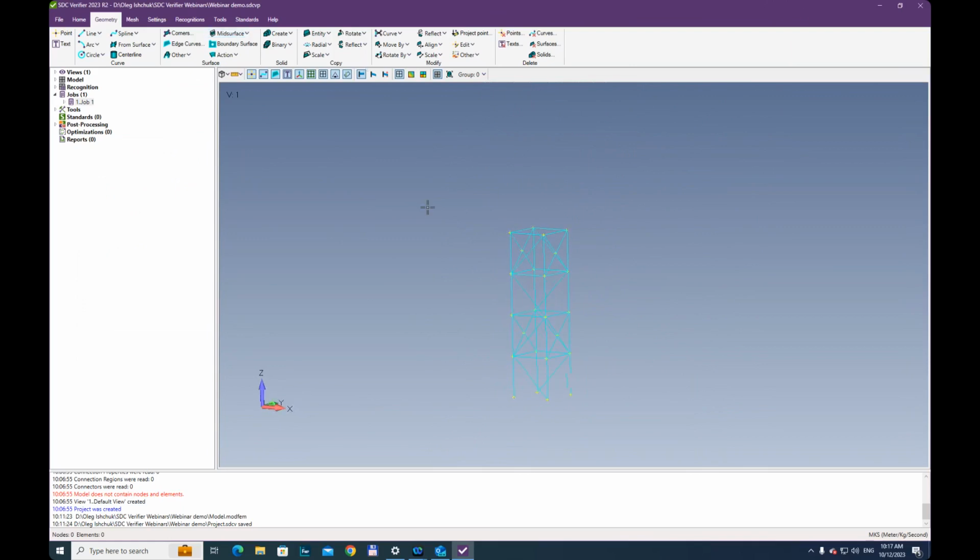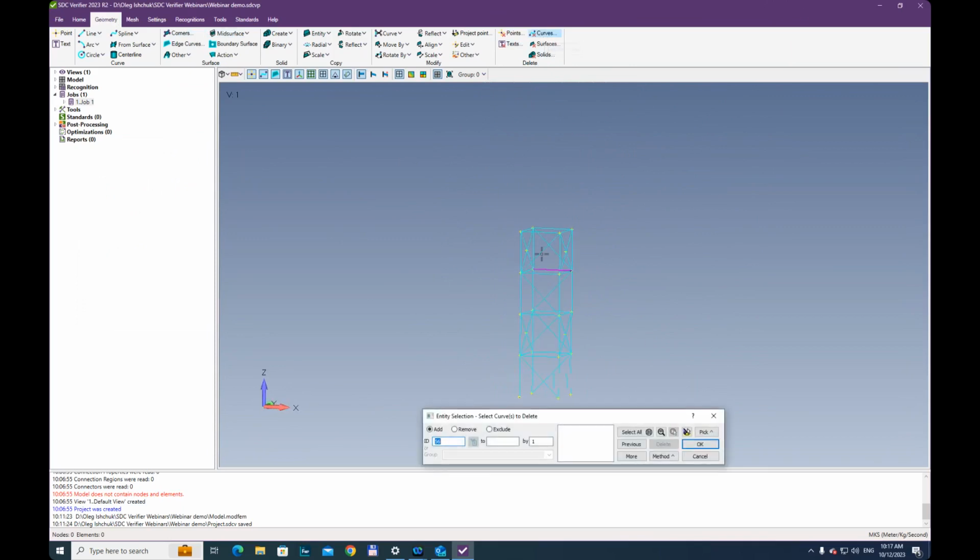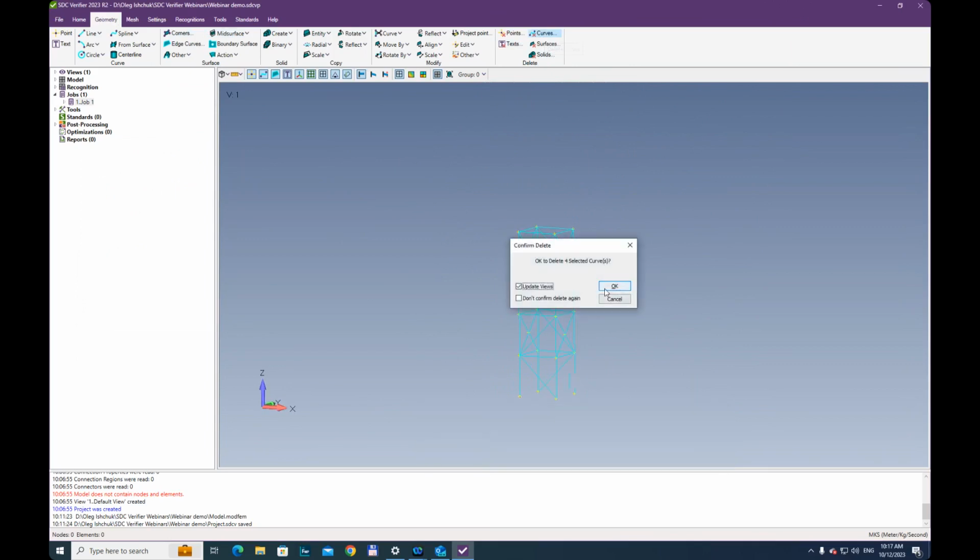Let's delete something. Delete is easy. In this geometry tab, we have the delete section, and I can select what I want to delete. Let's say I want to delete curves. So I remove these two, and maybe these two, not to make it look too messy. Press OK, delete it. Now these members are deleted. So on some sections, we have this crossing. On the other sections, we have just 2 diagonal members on the sides. I think that's going to be enough.